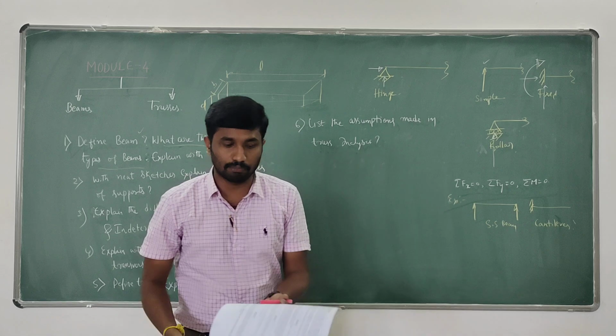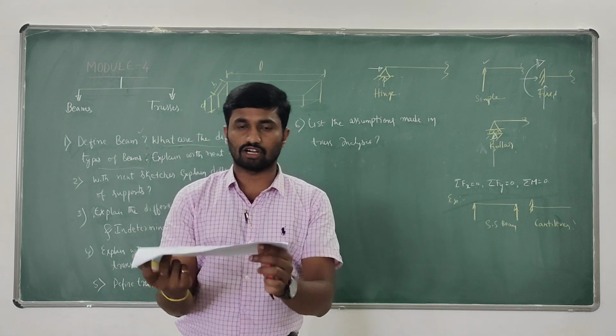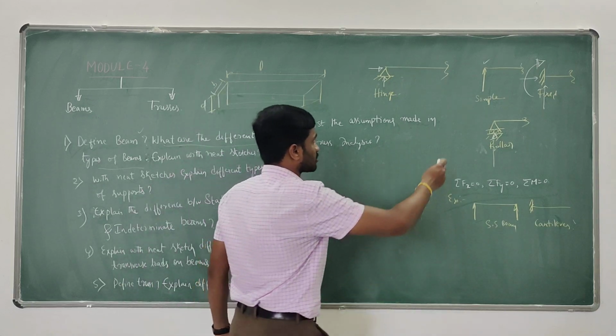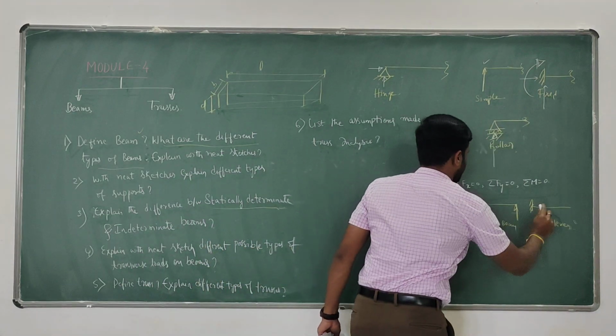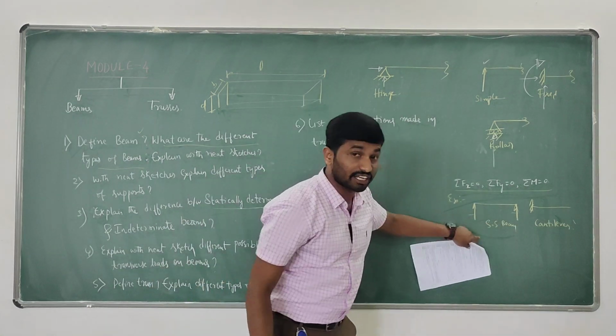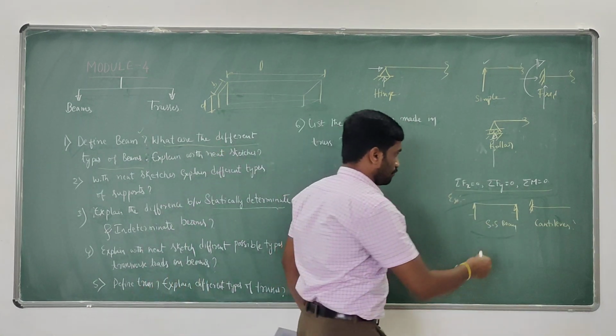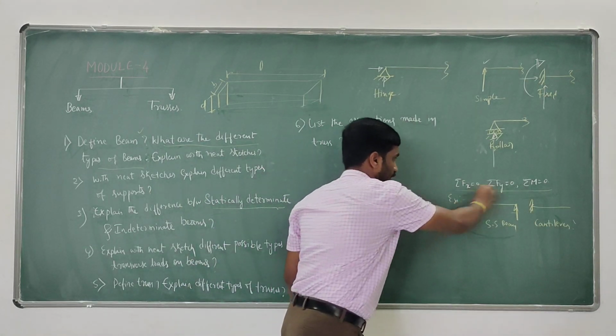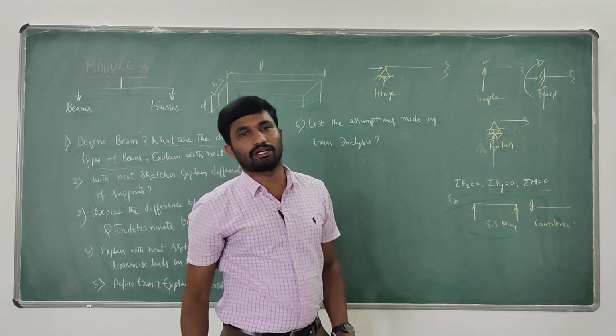What is meant by a simply supported beam? The beam rests on two simple supports. How many reactions? 1, 2. Only two reactions. Available equations are 3. Hence, this beam is statically determinate. Similarly, a fixed support: how many reactions? 3. Available equations 3. This is also statically determinate.